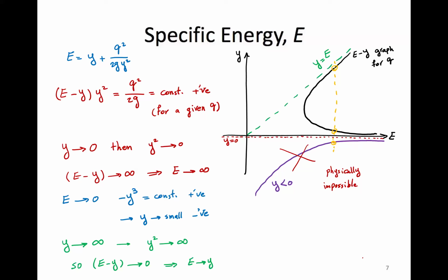So keep in mind, the specific energy equation is a cubic equation. You always have 3 roots, but the way it is set up, one will always be negative, and we'll stop talking about it from now on. We'll never talk about that negative root for obvious reasons, because from a practical engineering standpoint, there's no point. It's not relevant.